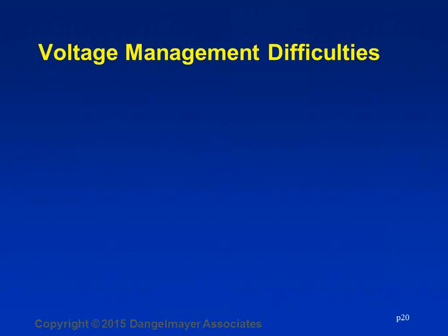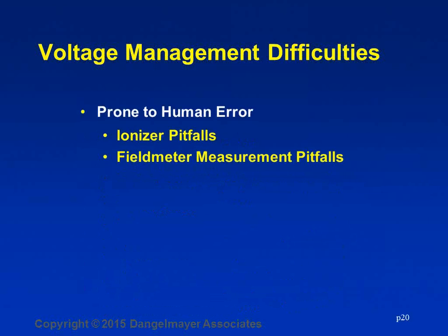One of the reasons is that voltage management becomes extremely difficult for extreme sensitivities. And here we're talking about also the human element. With voltage control techniques, you often use ionizers, you use field meters, and they both have considerable number of pitfalls.